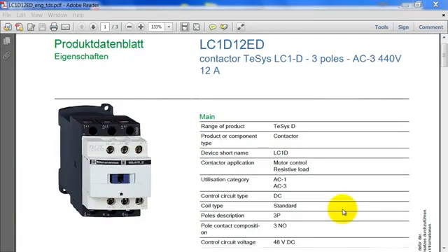In this video I'm going to show you how to create a 2D footprint of the part that you can see in the screen over here. This ties in nicely from the last two videos that I've done, where I showed you how to add manufacturing data, also using the same example as you can see in your screen, and how to create and associate a 3D part to that manufacturing data. So this week we're going to take it a step further and we're going to associate a 2D footprint to the actual manufacturing data that we've created in the last two videos.